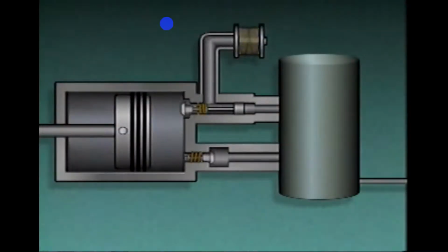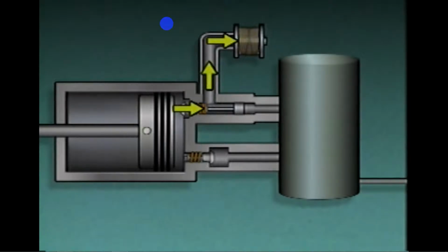With the inlet valve open, the gas that enters the compressor is pushed back out again and is not compressed. When the pressure in the receiver decreases, the pressure on the unloader piston also decreases, allowing the inlet valve to move back and forth normally, and the compressor resumes normal operation.